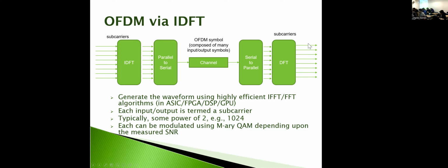It's a process we call water filling, because it's like looking at the floor of a pond, where sometimes it's deep and sometimes it's shallow, and you're going to fill that pond up with water. That water is going to reach an equal level, but there will be different depths here at different SNRs.